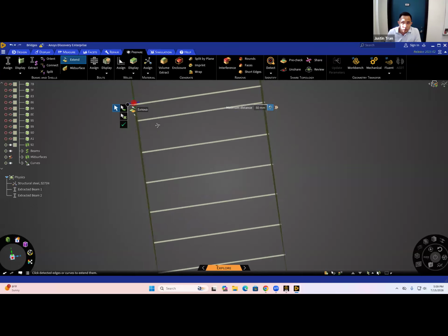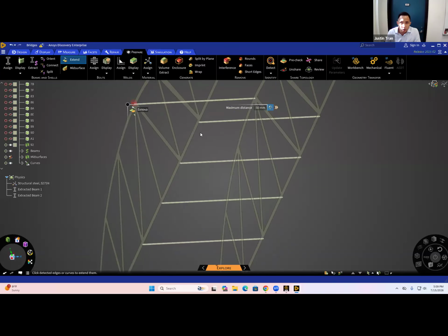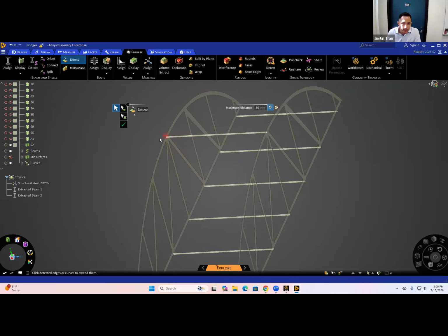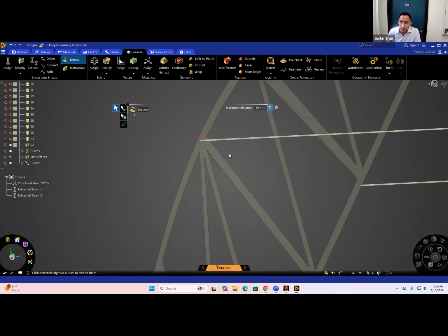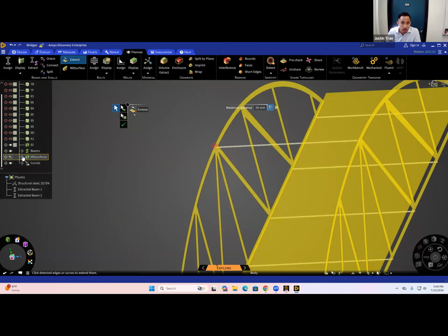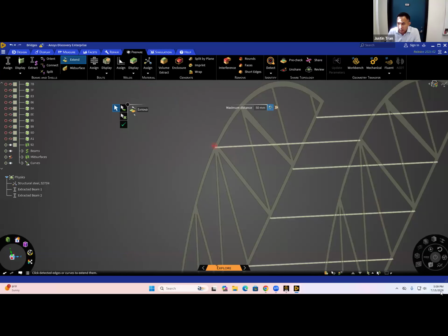Yeah, so this top beam, don't worry about it. Remember, this is just an artifact from the CAD file. This is not going to affect our results at all. The top beam should already be connected, so that one was already aligned with the bridge. The last part is going to be the road. Once you're done with the beams, and I think we'll do it at 5:10, we're going to move the road down and make sure it intersects with the bridge, and then we'll move it to ANSYS Mechanical.